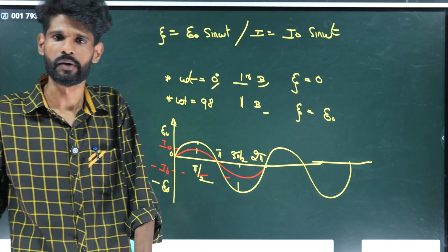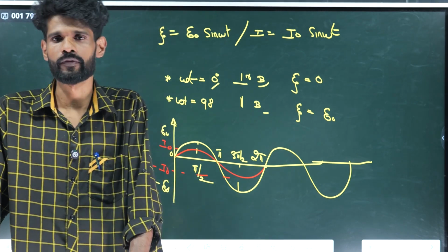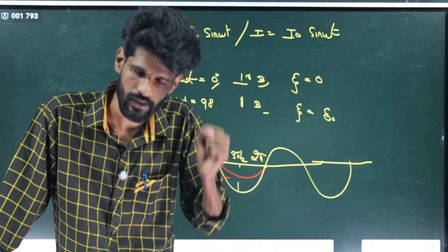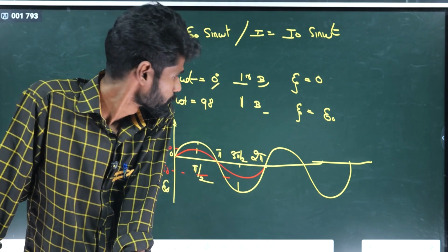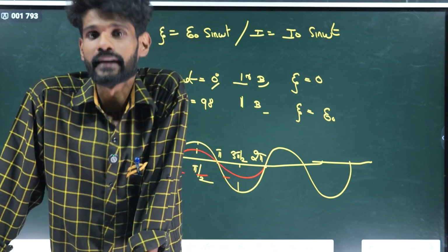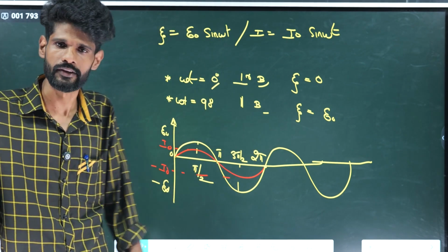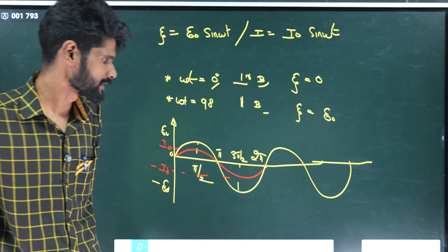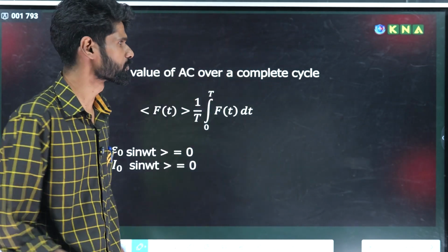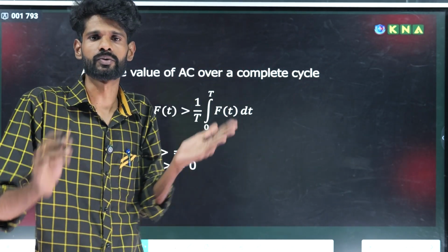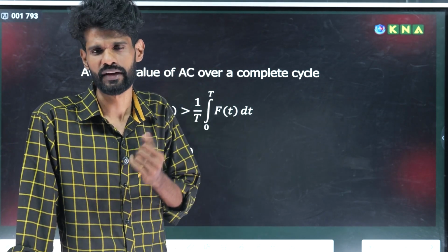The current amplitude varies because current is equal to EMF divided by resistance. So when a coil is rotated inside a magnetic field and EMF is induced, the direction and magnitude of this induced EMF and also current changes continuously. So that current is known as alternating current. That is how alternating current is produced when a coil is rotated inside the magnetic field. Here E is equal to E naught sin omega t, I equal to I naught sin omega t. At each and every instant the magnitude and direction continuously change.